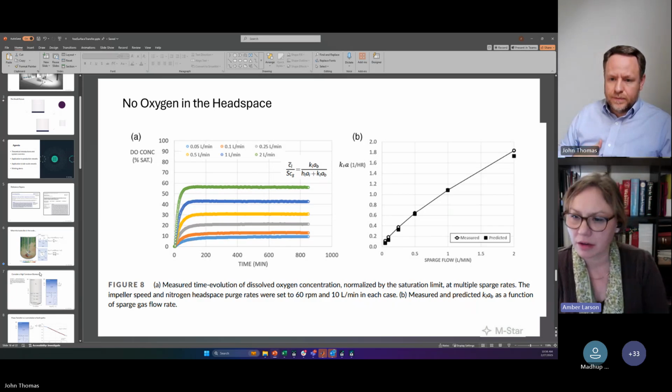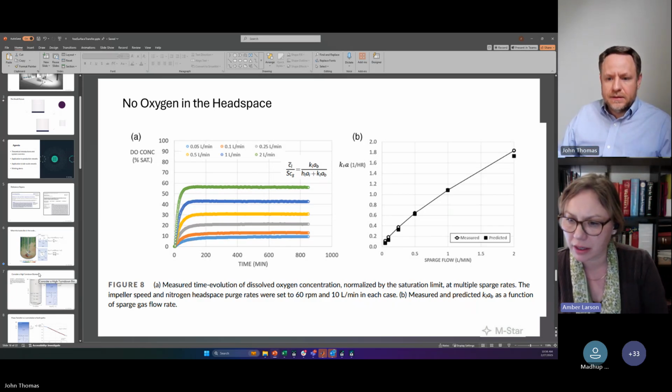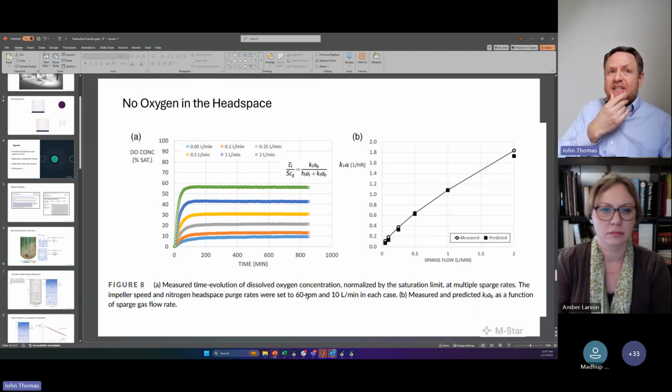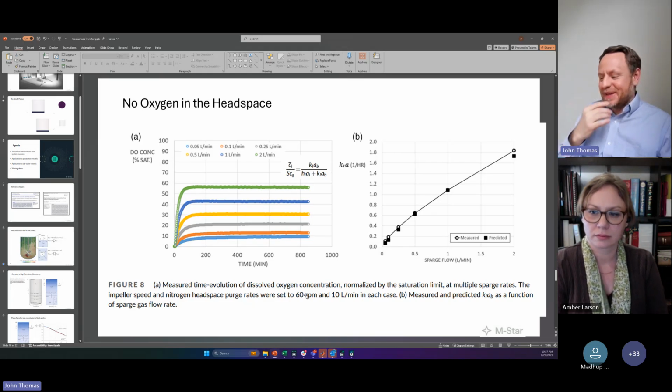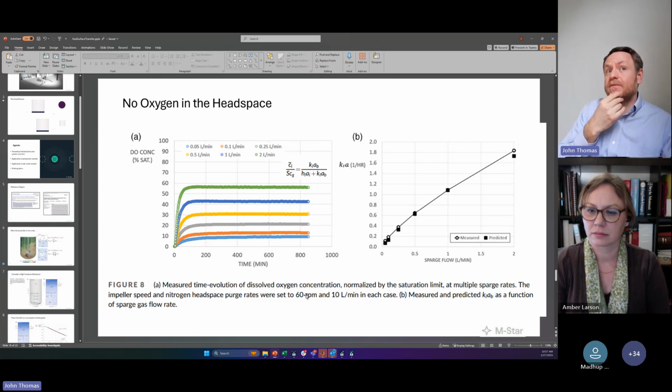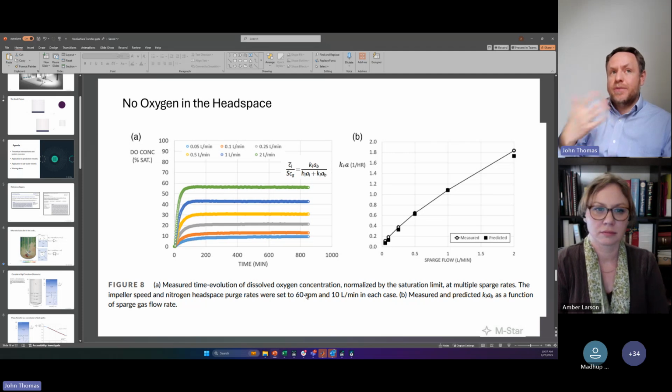Can bubbles be generated from the surface vortex shear and generate bubbles by entrainment of top airspace? Yeah, this is routine. We've given a couple of talks on this. Eric Jans has talked about things like self-aspirating impellers at AIChE, and I think we've got some neat work to maybe formalize about that. That's an extreme example, but to the person asking the question, it is the exact same physics.